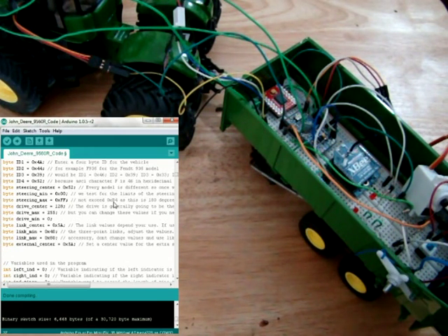Because if you set the maximum to B4 and you sent 5A, which should be 90 degrees, it wouldn't actually be 90 degrees, because your limits would have changed that. It would now be, I'm not sure, probably 30 something. So it's important that you set this to 0 and FF for this initial setup.